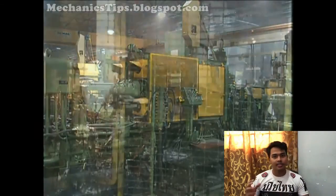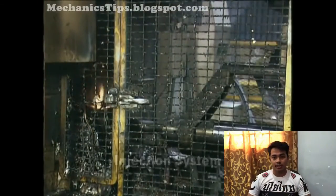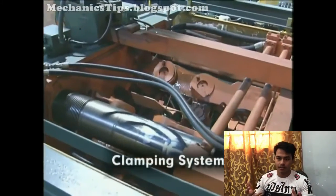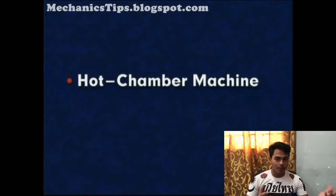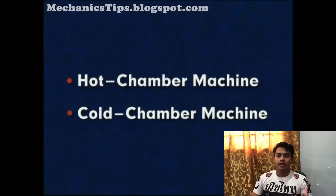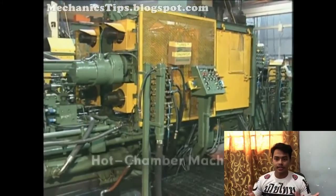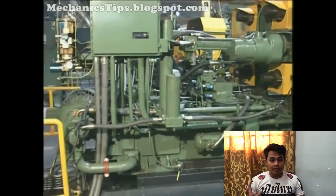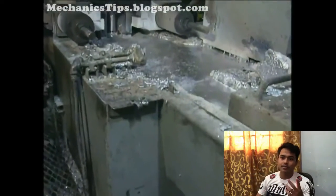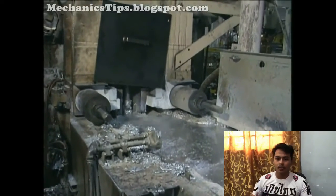Okay, now we go to the disadvantage of die casting process. The main disadvantage to die casting process is very high capital cost. Both the casting equipment required and the dies and related components are very costly as compared to most other casting process. Therefore, to make die casting an economic process, a large production volume is needed. Other than that, the process is limited to high fluidity metals and casting weight must be between 30 grams and 10 kilograms.